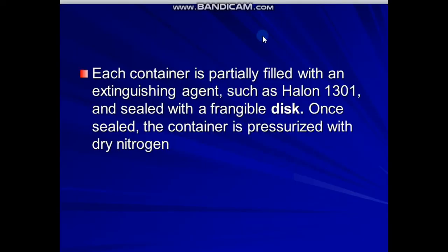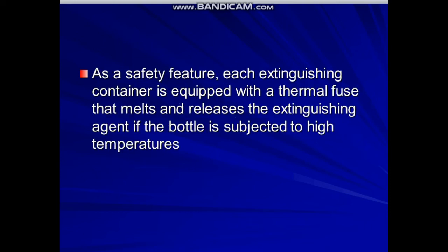Each container is partially filled with an extinguishing agent such as halon 1301 and sealed with a frangible disc. Once sealed, the container is pressurized with dry nitrogen. As a safety feature, each extinguishing container is equipped with a thermal fuse that melts and releases the extinguishing agent if the bottle is subjected to high temperature.